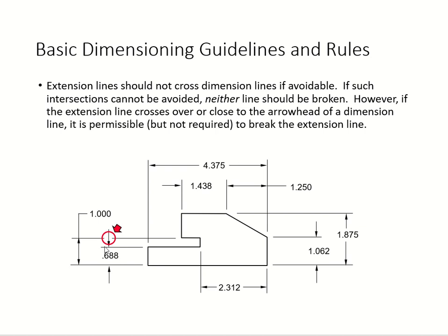Okay, so the very first one, don't cross over. Yeah, so don't draw your extension line crossing your dimension line. You want to avoid it at all costs. If you cannot avoid it, you can do it only if you are not able to avoid it.